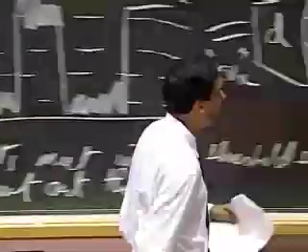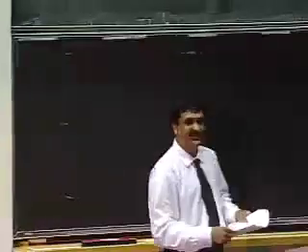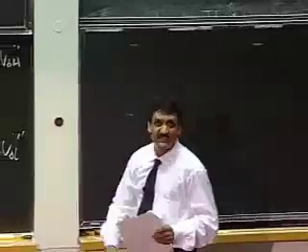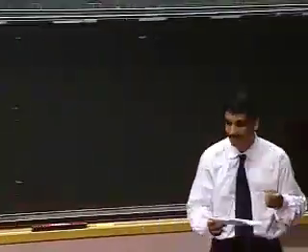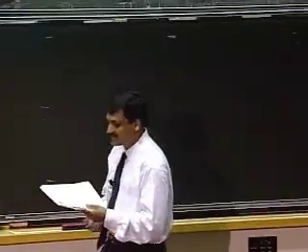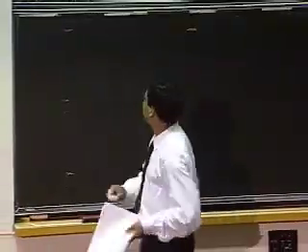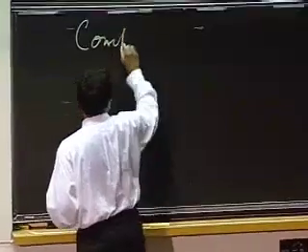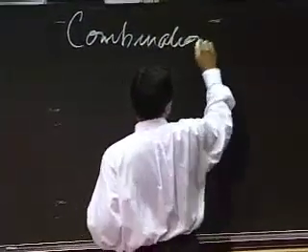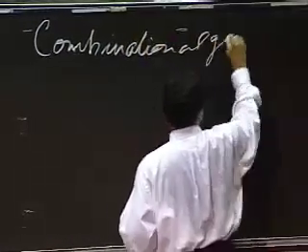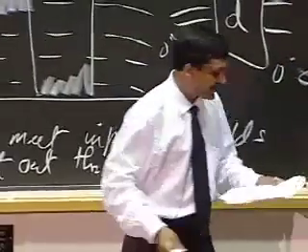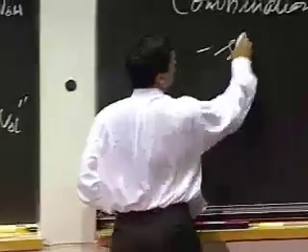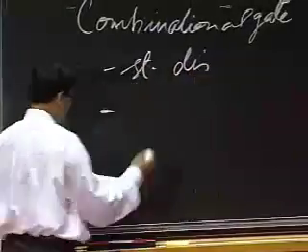Okay? So that leads us to, given this sort of voltage thresholds, we now move into the digital world. And in the digital world, we can build a bunch of digital devices. The first device we will look at is called a combinational gate. A combinational gate is a device that adheres to the static discipline, page 11.